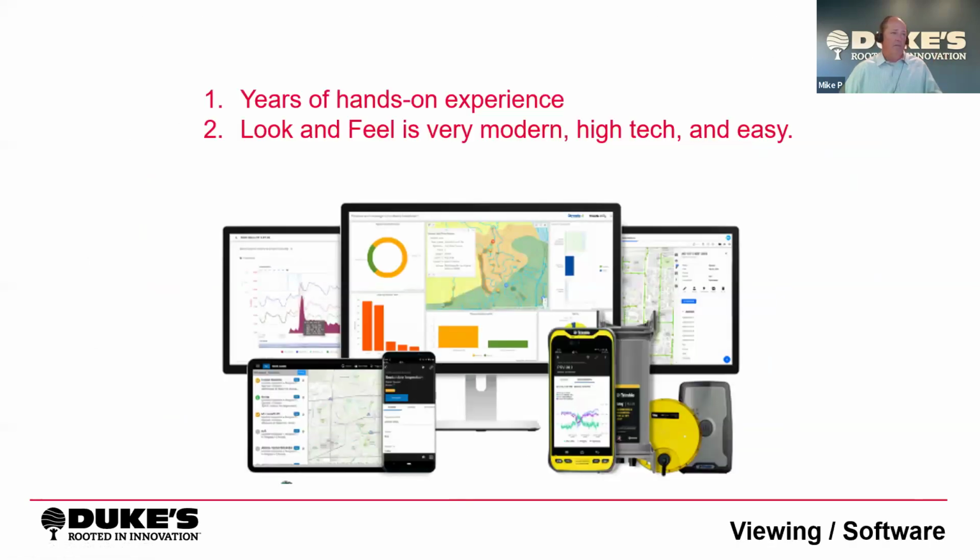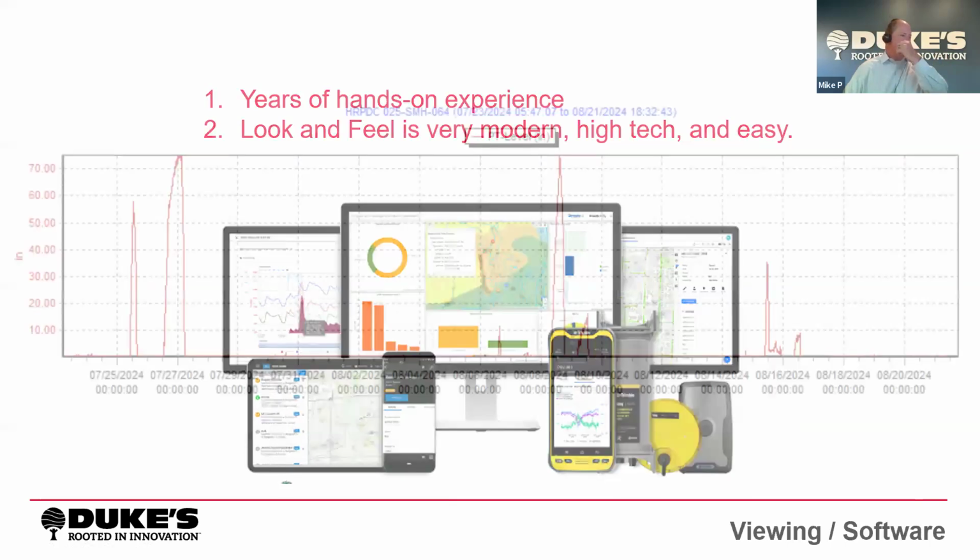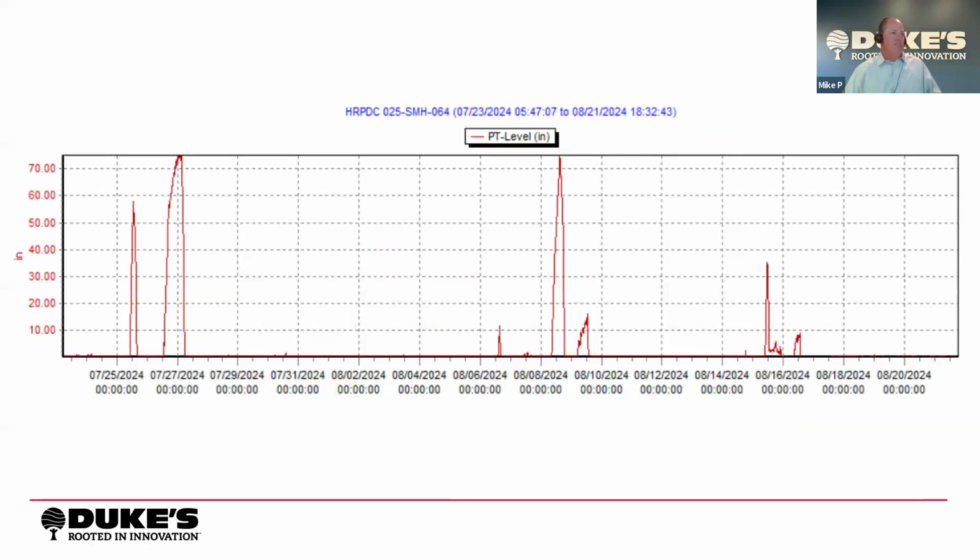Sitting behind the hardware is a very sophisticated software set. I call this kind of the iPhone generation data, and it's a nice look and feel as far as the data is concerned. This is a snip from a graph here. This represents about a month's worth of data. And of course, I picked one out that's seeing surcharge. In this case, this is in units of inches. You can see over 70, this is about 6 feet, right? Not an overflow, but maybe something for the utility that has this to know, right? So some stuff going on.